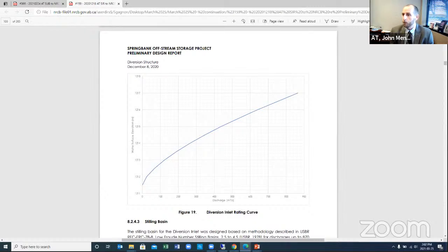We'll have several that are located and mounted to the debris barrier in and around that location that can be above the water level using ultrasonic measurements to shoot down towards the water surface elevations to capture those locations. And we'll utilize our hydraulic modeling tools to relate that elevation to the rating curve, and then allow the operators to make decisions with regards to operations.